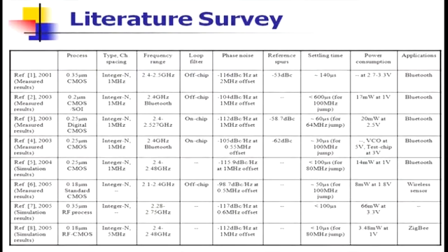So as if from your side, my transmitter or my receiver is always on, because I am changing it very fast. By using that perception of vision, the frame is changing very fast, so it looks like a steady state. Like a frequency synthesizer, I am hopping the frequency very fast. So the settling time determines that. Okay, so the higher the frame rate or the higher the hopping frequency, the less settling time you should have. How much? I said for Zigbee, it is 120 microseconds.